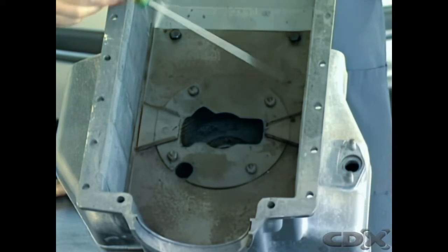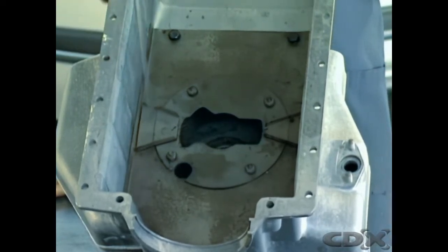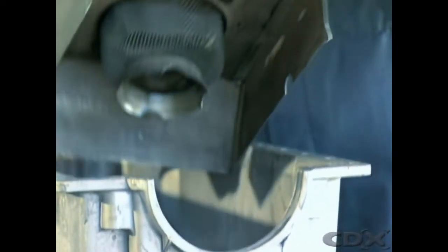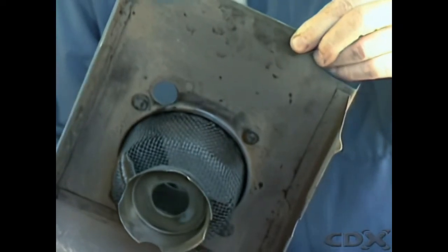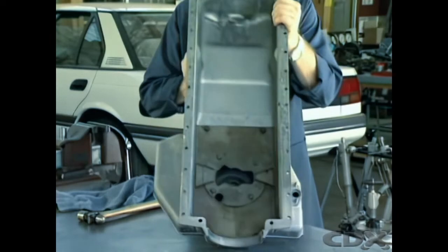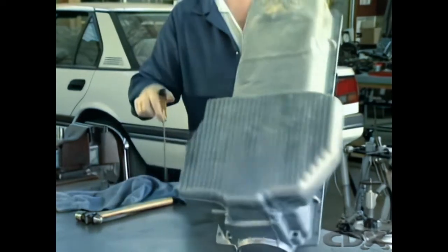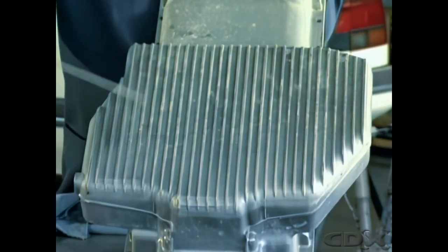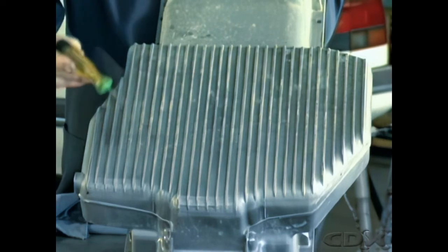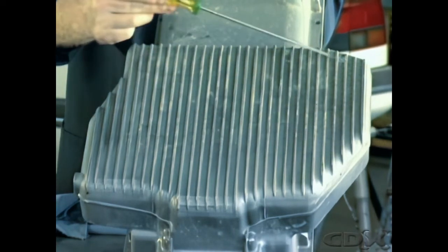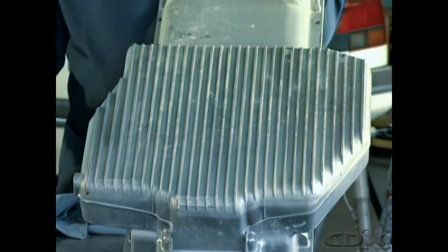Some high-performance vehicles have a windage tray fitted to prevent churning of the oil by the rotation of the crankshaft. Baffles prevent oil from surging away from the pickup during cornering, braking, and accelerating. The sump's large external surface area helps heat transfer from the oil to the outside air. In some designs, the sump is an aluminum alloy casting with fins and ribs to assist in this heat transfer.